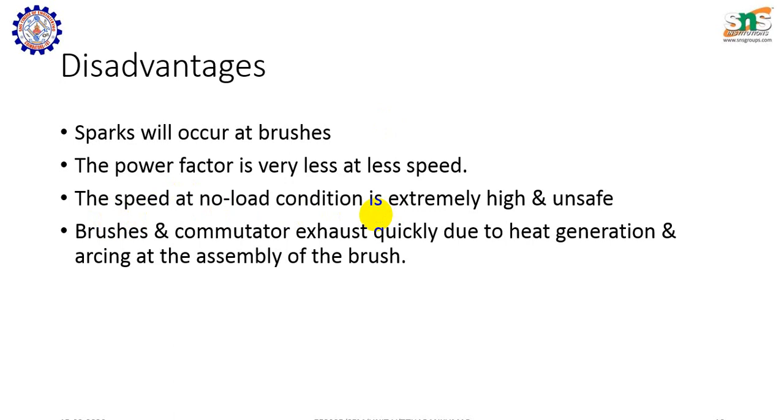We have seen speed control of a DC series motor in laboratory experiments. Normally a series motor will be started in off-load conditions. If we are not loading it, initially it starts at infinite speed, so that the brake drum can even move away and it can cause damage to the person or the equipment itself. So a series motor should always be started with half-load conditions.